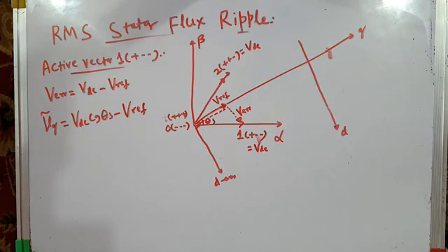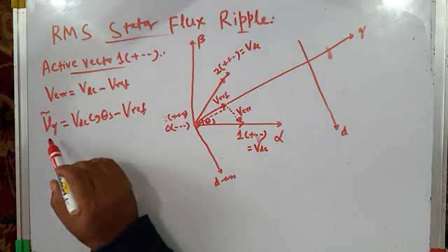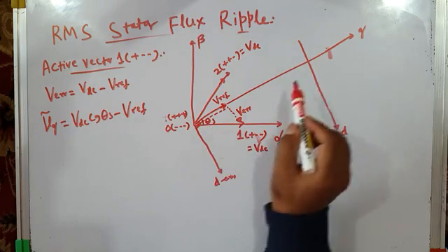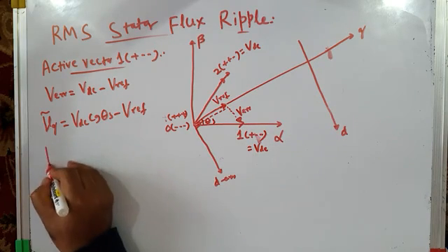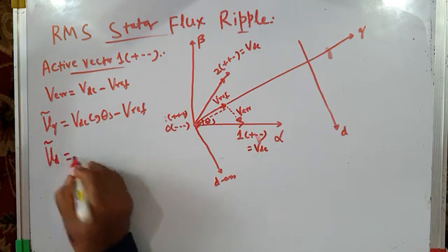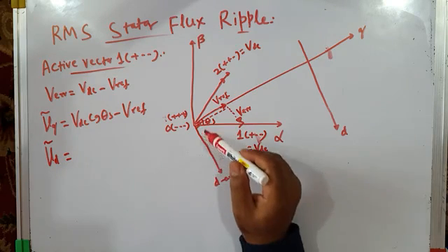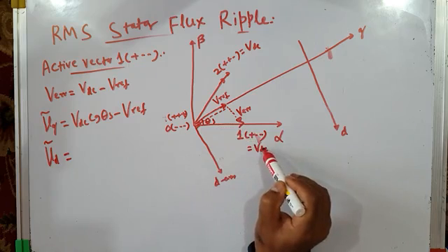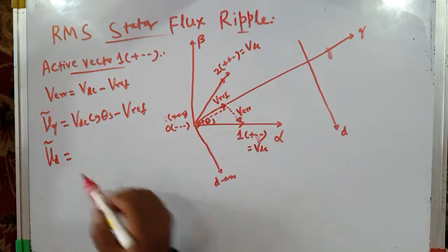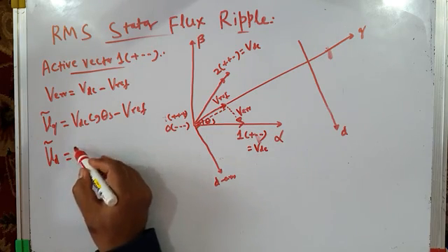So this is the Q component of the error voltage vector along Q axis. What about the error voltage vector component along D axis, Vd tilde? Along D axis, what is the applied voltage vector? Applied voltage vector is 1, which is VDC, and its component along D axis is VDC sine theta s.